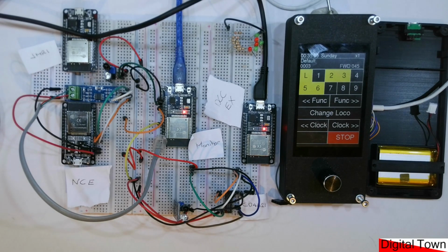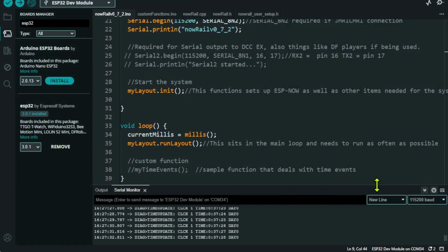However, something came up, and the item that came up was completely unexpected. I must admit, it caught me out. Usually when you start your Arduino IDE, down in the bottom right, you'll get some messages about some of your libraries needing updating, or some board managers needing updating, or whatever. And usually you just don't think about them, you just click on them and install them. However, I've tended to not update libraries because certain libraries I've got, if you update them, they cause a problem.